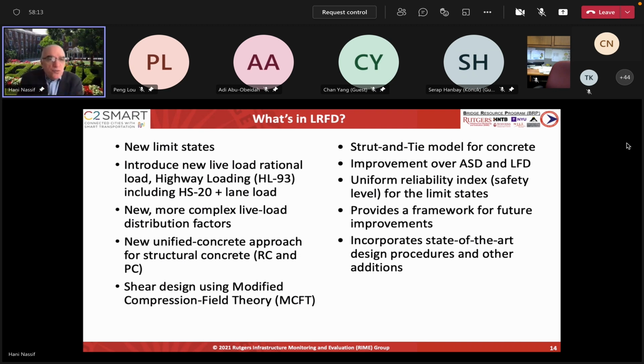Dr. Kulicki said, what about if we do both of them together? Put the uniform load and then add the truck on it, and you put the truck where it will maximize your moment, right? And when we tried that combination, it looks like it envelopes everything, even the exclusion vehicles that you have seen. So the HL93 came about in trying to be a practical way to envelope most of the truckloads that you see on the road these days.